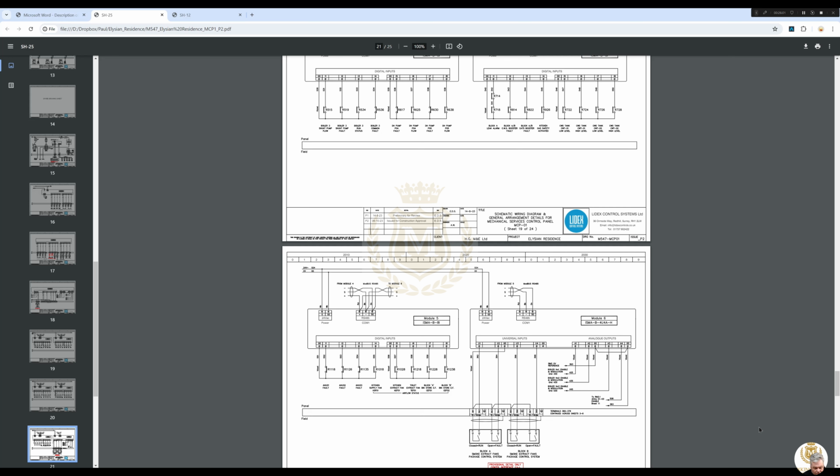So the 4U's is going to be the close, run and open fault of smoke extract fan of block A and block B. And then we've got a boiler number 1 enable modulation, boiler number 3 modulation, and AHU 1 to 3 enable using an analog output.